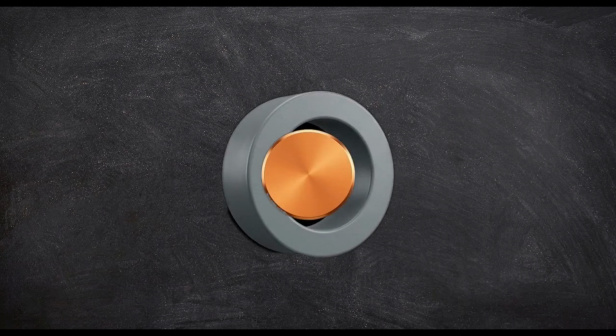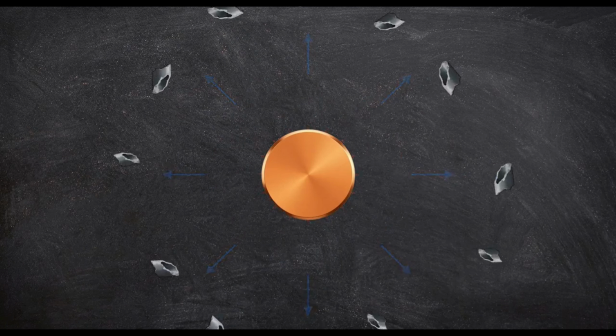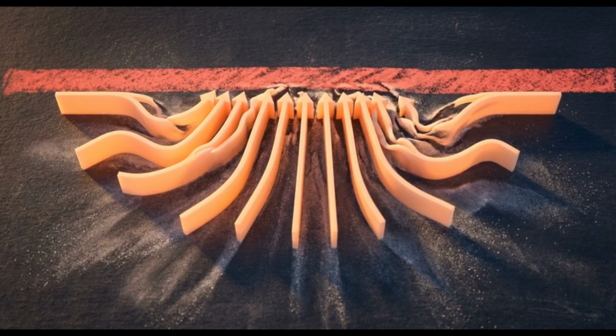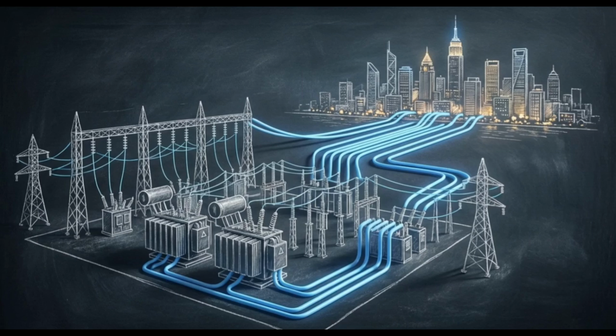Safe operation requires strict thermal equilibrium. The red arrows must dissipate into the environment at the exact same rate, shown by the blue arrows. If heat generates faster than it's absorbed, equilibrium collapses, melting the insulation. This physical limit of heat transfer is what engineers call ampacity. It is a thermodynamic rating that dictates the safe operational capacity of any electrical system.